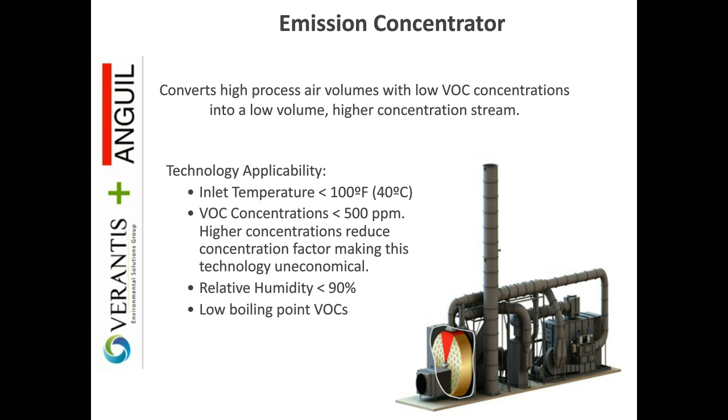Also, the semiconductor industry, extremely common for a different reason there. Now, those airflows in the semiconductor industry can be very large as well, but they also tend to be very prone to pressure fluctuations, where the RTO inherently can have a very small pressure fluctuation that can cause operating issues back at the actual process. For those applications, we would install this concentrator wheel between the RTO and the actual process.